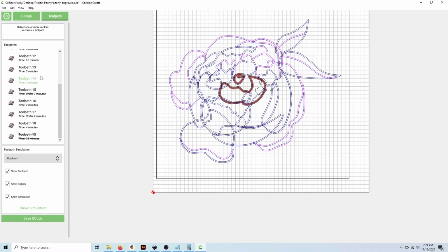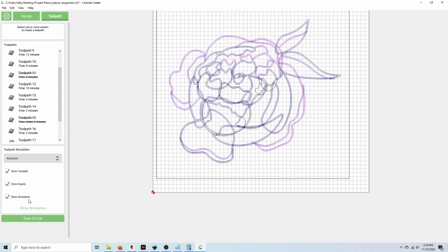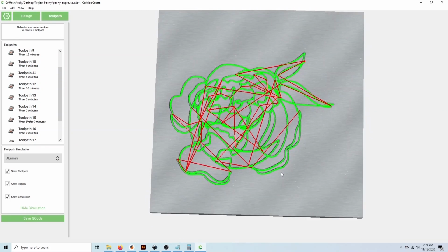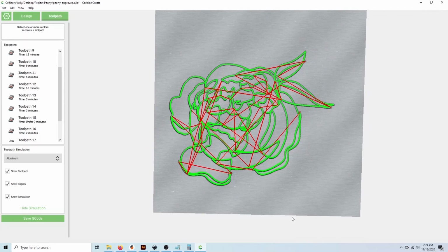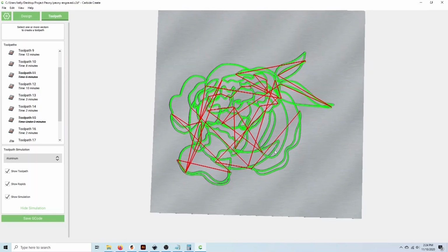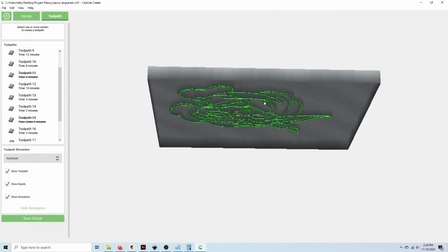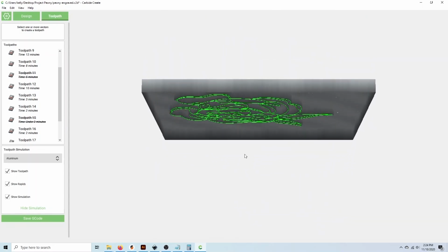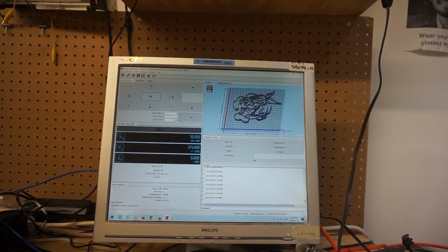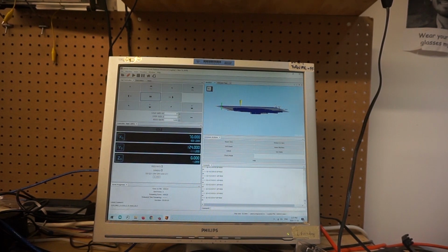So I tried disabling some toolpaths to see what that would do to the design. I think I selected a contour twice, or a few contours twice, and after disabling it, I noticed that everything's cutting to the same depth now. Okay, so we're back. I still have the old G-code open. You can see it's unusually deep for one area of my flower.